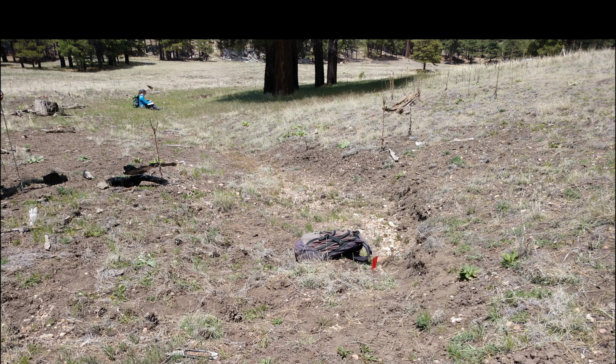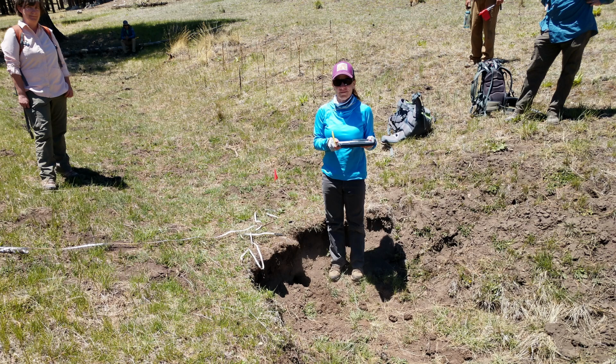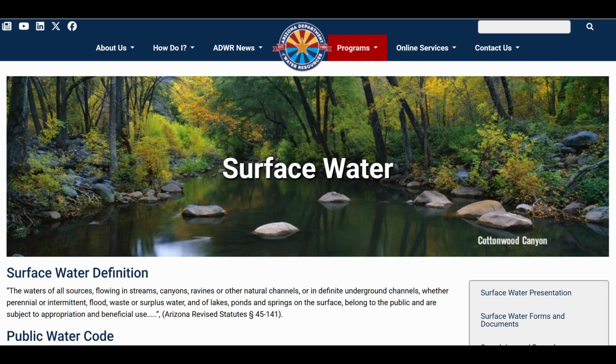The head cuts that were present in the valley were draining historic wetlands and causing erosion. The soil washing downstream from the head cuts was filling the shallow wetland basins that were present. We planned to control the head cuts along a 1-mile stretch of the ephemeral stream on the Dye Ranch by using both the slope and armor technique and the vertical grade technique. To comply with water rights regulations, we followed direction that the project could only be implemented if no water was impounded and the size of the wetlands was not increased.